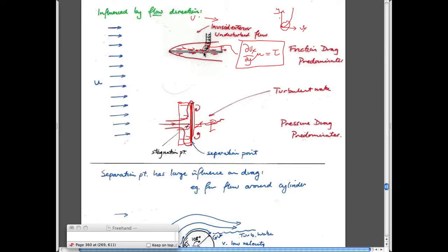And so the point is that at this location, there's some kind of shear force applied on this boundary, and to be able to hold that plate in place, you'd have to apply a force on that plate equal to S, which would be equal to 2 times the shear stress times the area of the plate, right? Top and bottom. So the plate has an area, it's top and bottom, it has an average shear stress on it, and you can get the force that's applied on that.